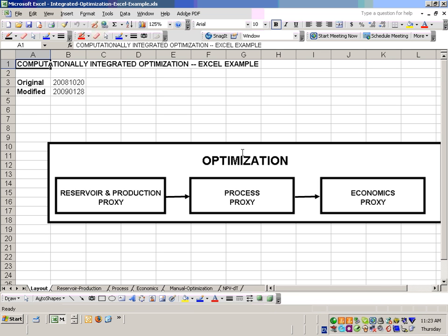There's a material balance there, which says that as we take out production, in this case from a gas reservoir, the average pressure falls. So the reservoir has a tank material balance, a gas reservoir equation, and a pipe flow through tubing built into that one model. And then we're going to have another model, which is the processing.